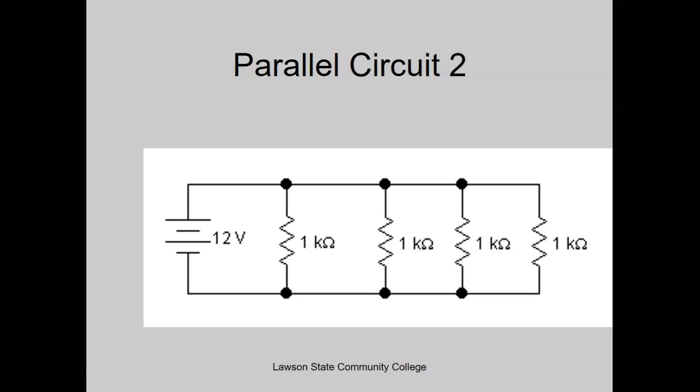So same thing here. If I have an open on any one of these circuits, again, it will change the overall. If I have a break in the circuit right here, it's going to double my resistance in the total circuit. And I'll show you why. If everybody's got all this over here, we're going to erase it, and we're going to talk about the differences between opens and shorts a little bit ahead of all this, just because it kind of fits in what I'm trying to explain. All right, so we know everything's going to be 12 volts.